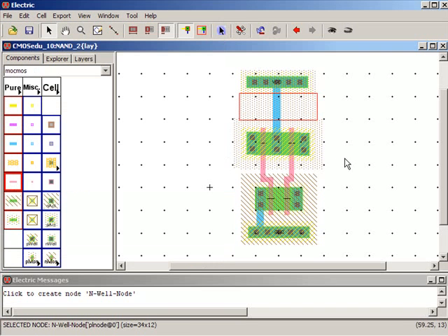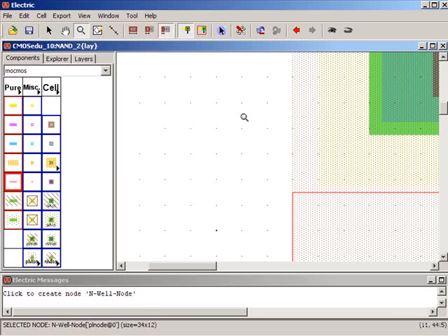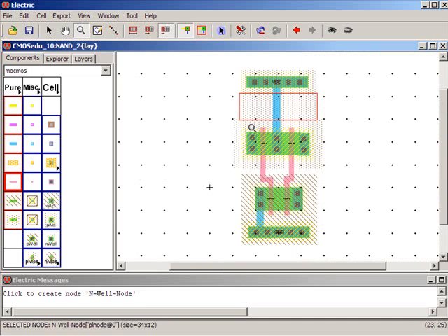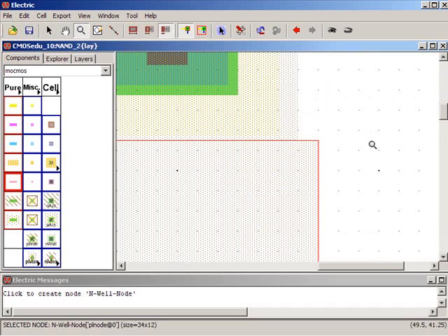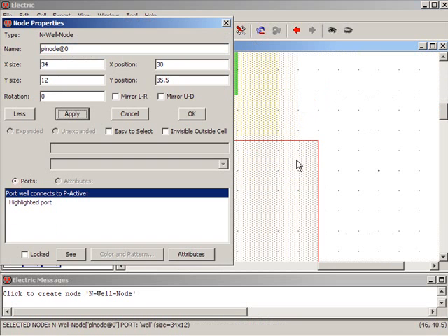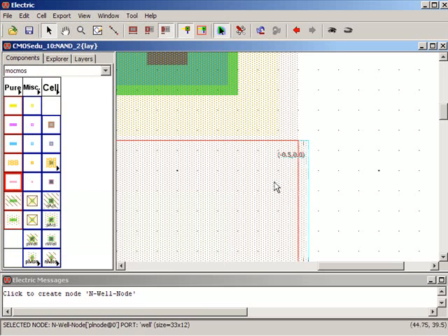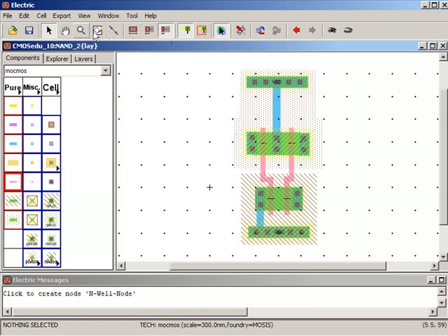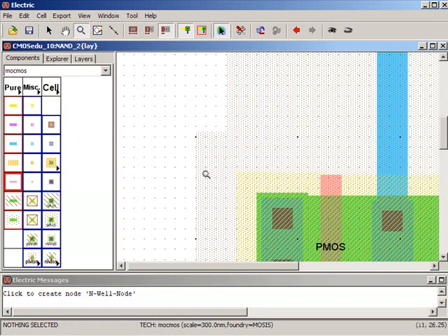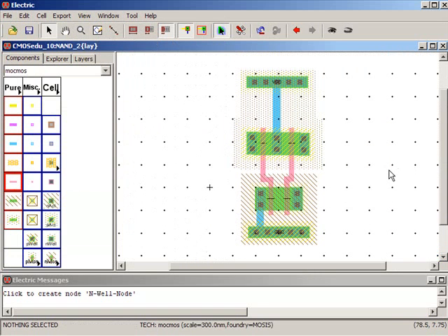Okay, so, and this layout again, I'm such a stickler for nice looking layouts. Let's fix it. So that looks fine. Okay, it needs to come over one here. Notice I can't get that, so I gotta go to the special select. So I need to change this Control I to 33. Apply. Move this over. Fit. Zoom in here. Okay, so now what I'm gonna do, just to fit, I'm going to try to clean up the layout. I'm going to go ahead and get rid of these connections. Delete them.